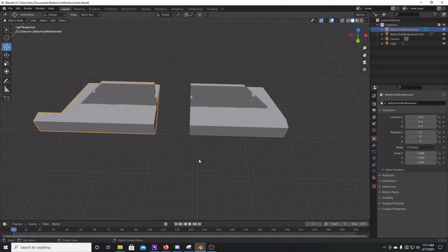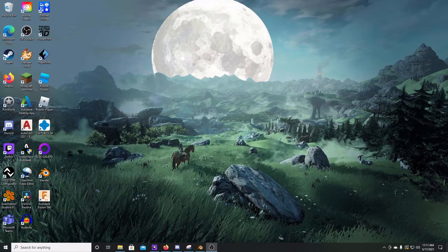It doesn't like to very easily recombine as a single face, and if it's not a single object, it's not going to export as an STL. So in order to fix that, you have to download some other kind of CAD software. For me, I downloaded Fusion 360.